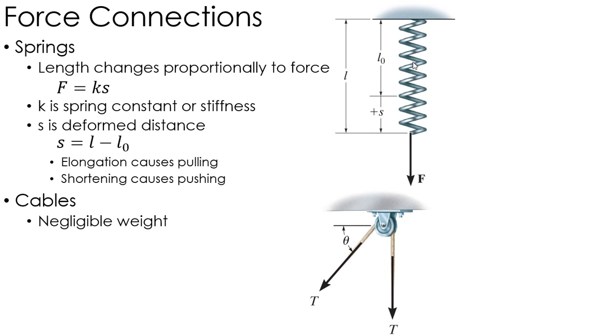The other thing we want to talk about is cables, and we've already dealt a lot with cables. Just a few assumptions that we always make about cables. The first one is that the weight is negligible, so we don't have to worry about gravity acting. Generally, they're much smaller than the loads we're dealing with. The other thing we assume is cables don't stretch. Obviously they stretch a little bit in real life, but not an appreciable amount that we need to worry about. Not like a spring would stretch. So we assume cables do not stretch.